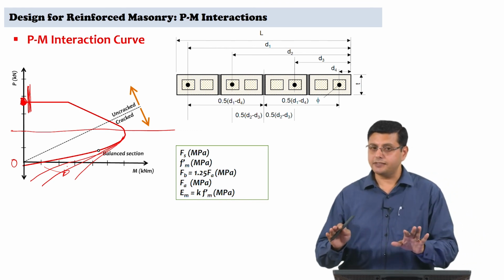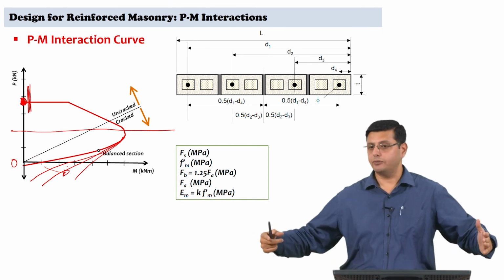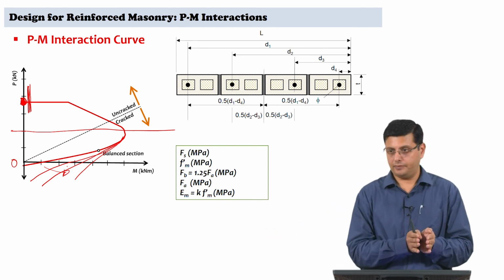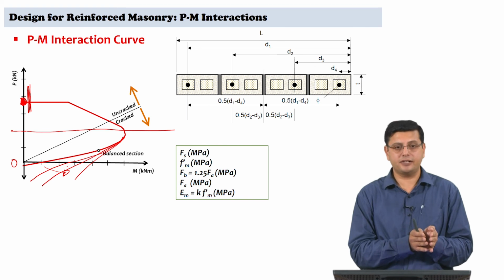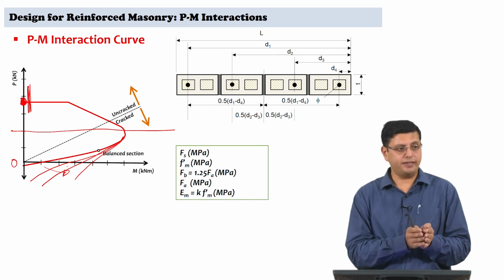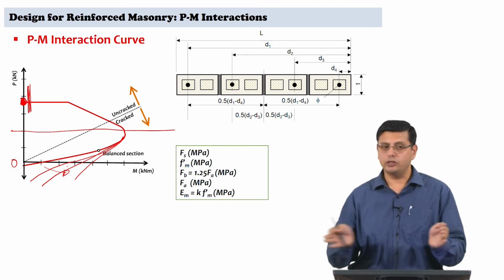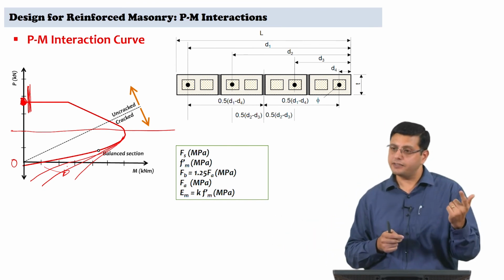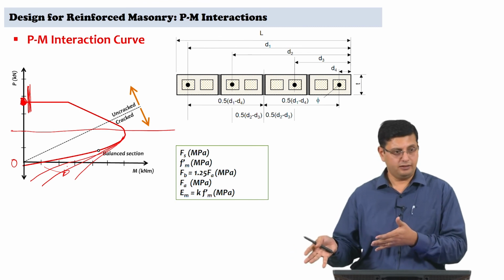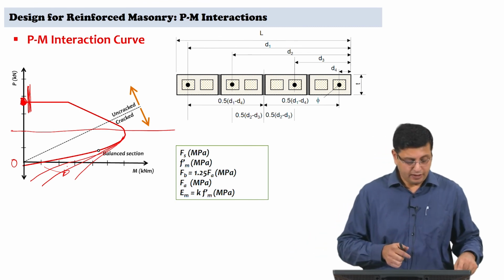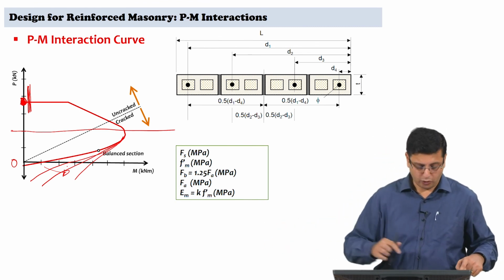of course, the axial stress ratios are small because we are looking at an entire wall cross section. If it were a column, these axial stress ratios will be high. Would you agree? If the entire structure were not made out of load bearing walls, were made out of columns, the axial stress ratio will typically be higher for a similar plan area. So, it is because of the presence of load bearing walls.